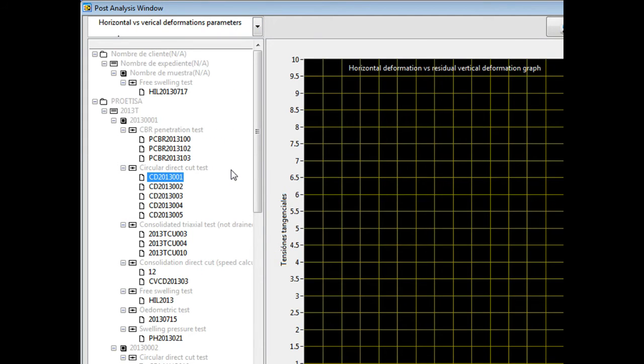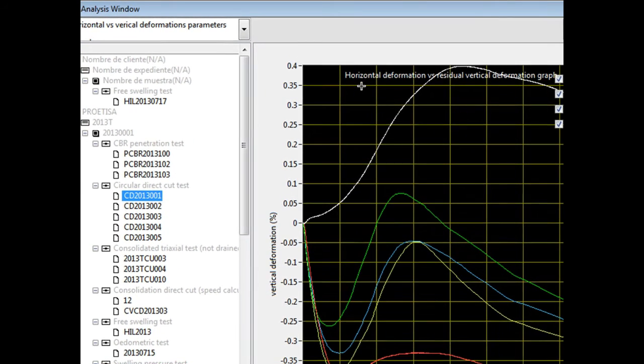You also can see here the horizontal deformation versus vertical. This sensor against this sensor. What you can see with this is something that we call dilatancy. You have a sample, bottom, top, and when you do this, maybe do something like this, because the grains can go up, down, out, up. This is called dilatancy, and this is what you can see here.